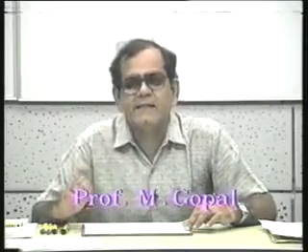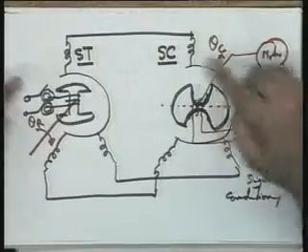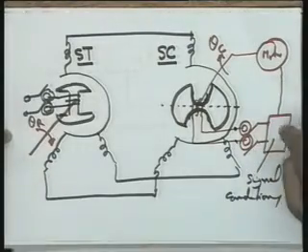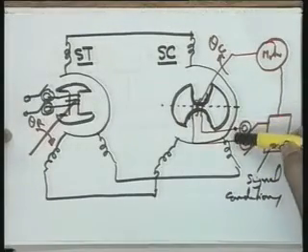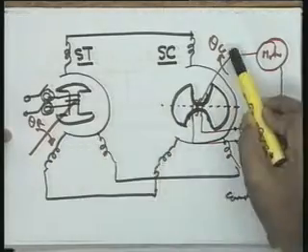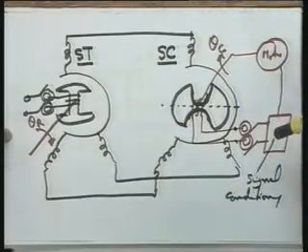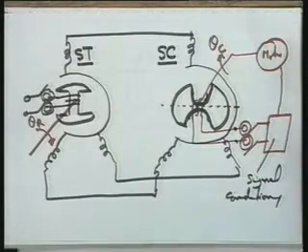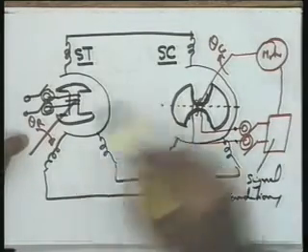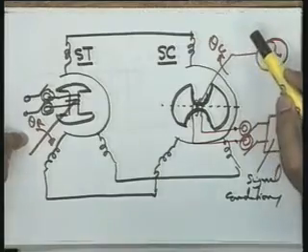So, exactly the identical arrangement, identical equation will come with the synchro pair. The only thing is that the synchro pair is an AC device and is acting on high frequency signals. In this particular case, theta r is the reference position and theta c is the controlled position, and you want to use this device as an error detector, so that the signal available here is an error signal, a signal proportional to the difference between theta r and theta c. And this is what we are going to see: how do we get a signal which is proportional to the error between theta r and theta c.